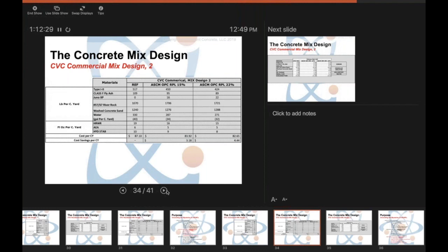Conducting the mixes in the lab, conducting the mixes in the field, call it good concrete practices, but good concrete practices always dictate that we try out these things in a safer setting, something that has a lower impact. So if something bad happens, let's say if we have to dial in the mix, what we did in the lab might be a totally different monster than what we're doing in the field. We have that chance to dial things in.